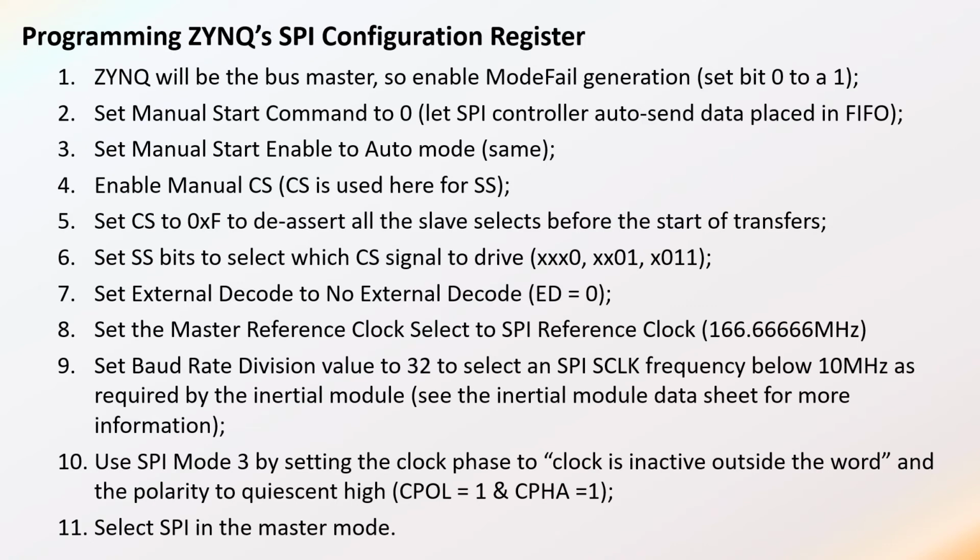So the reason we want to have a manual chip select in this project is because, we'll see a bit later, the device we're talking to, which is the nav chip that's got an accelerometer and gyro and magnetic compass, magnetometer, has two separate SPI ports. So the reason we're using a manual chip select is so we can manually choose which of those SPI ports into the device we want to drive.